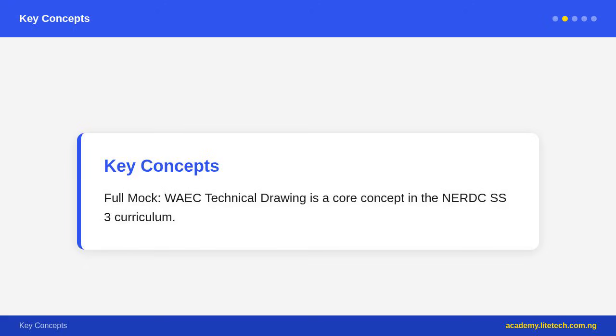In a section through a gear, the teeth are shown in a simplified rectangular form, or often the section shows between teeth spaces. Meshing gears, in a drawing of 2 meshing spur gears. Their pitch circles are tangent, touching, at the pitch point. The addendum of one gear overlaps the dedendum of the other at the pitch point.